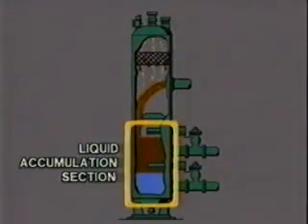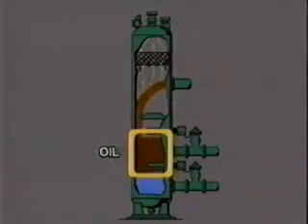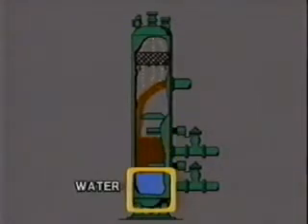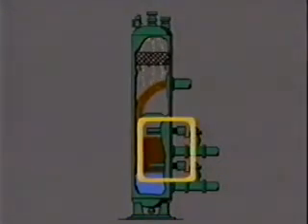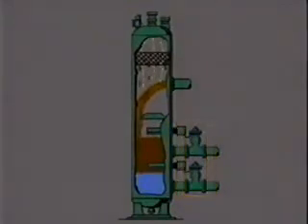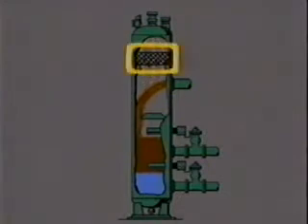The three-phase vertical separator has construction similar to the two-phase vertical we examined earlier. The major difference is in the liquid accumulation section. Here, the top portion of the accumulation section collects oil, and the bottom portion collects water. Both areas have their own liquid level controllers and liquid level control valves. The well stream enters the vessel in the upper portion. Stream direction and velocity are changed by baffles. As the gas and liquid vapors rise, baffles or straightening vanes and a mist extractor remove the liquid droplets. Gas leaves the separator near the top.